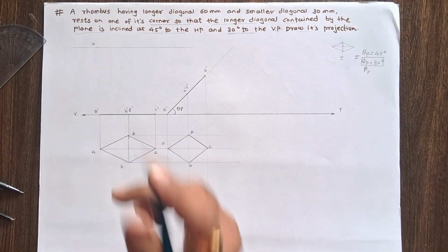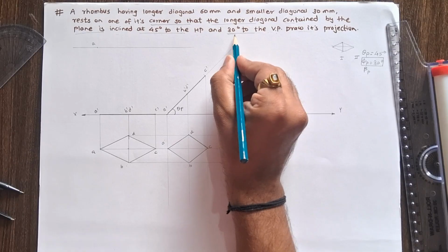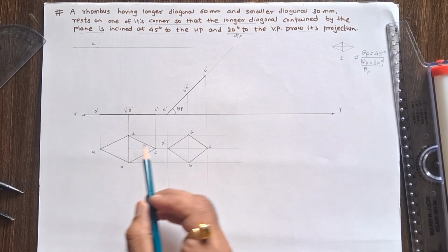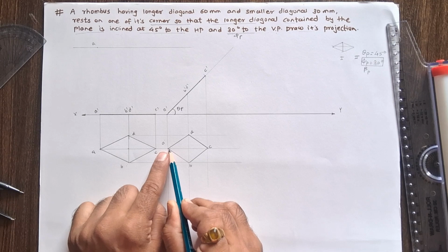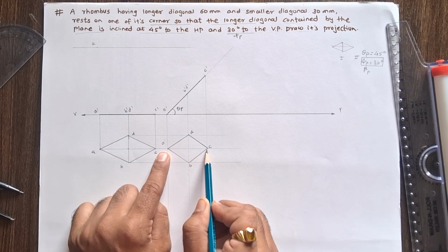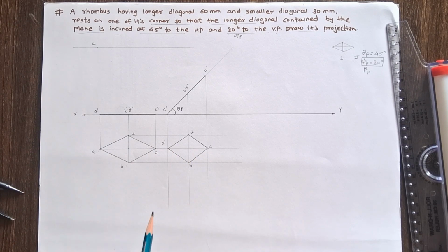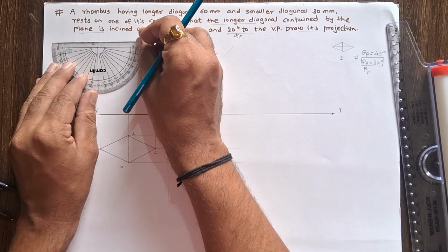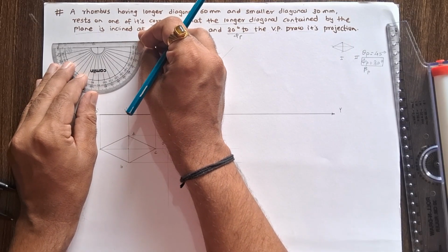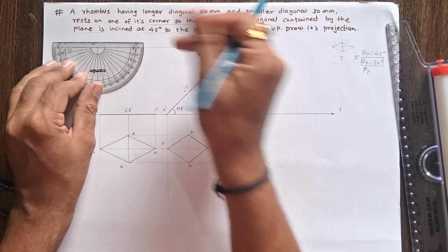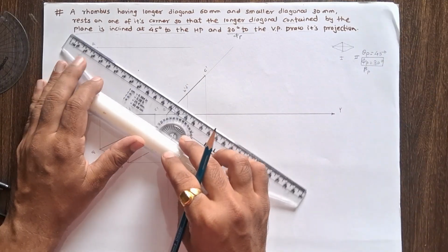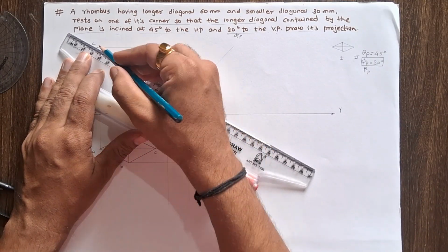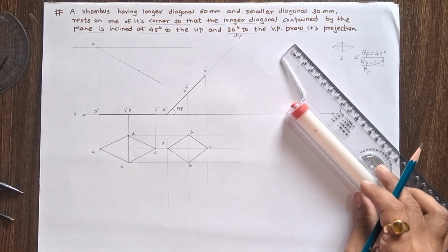Now, this is a point. This phi plane angle is given, so this phi plane angle is made with a true length. But in the second stage, this AC distance is an apparent distance. So here we are required to find the beta angle, or apparent angle. For that, first mark a 30-degree angle using a thin line. Mark this angle.